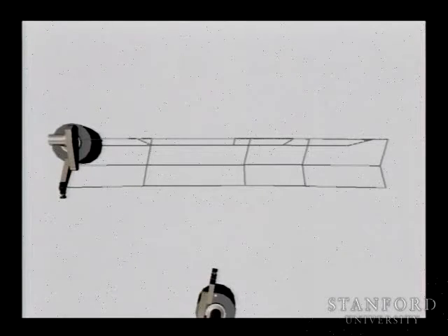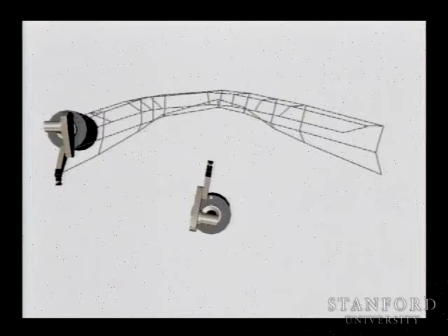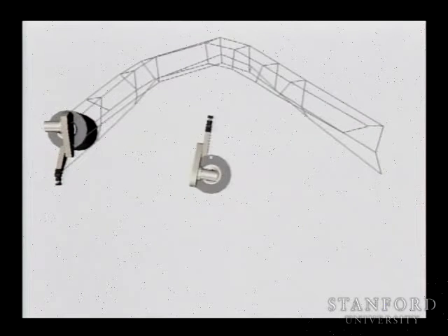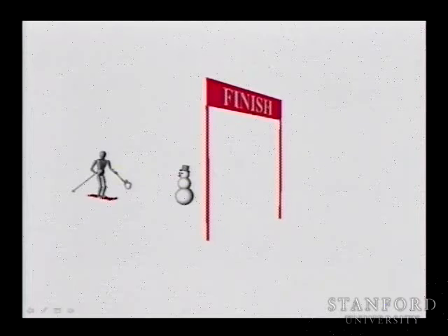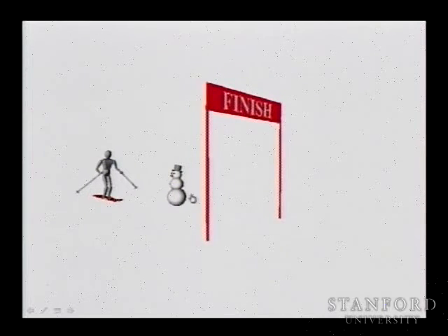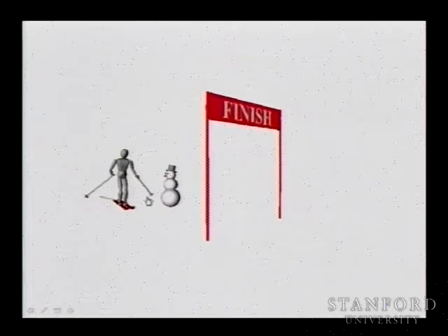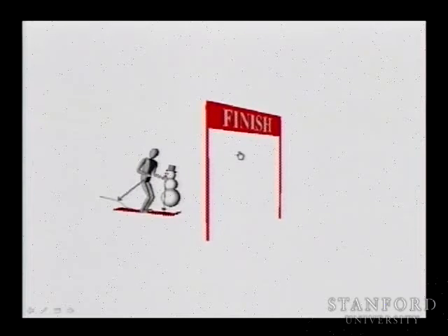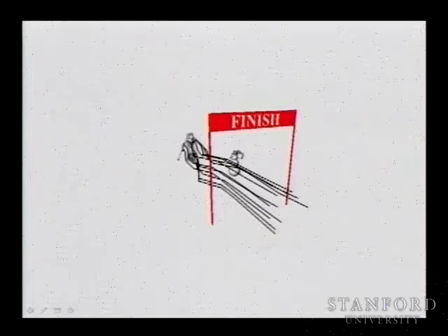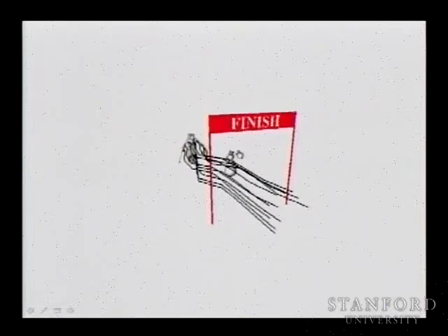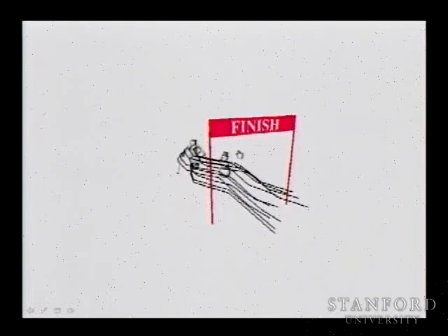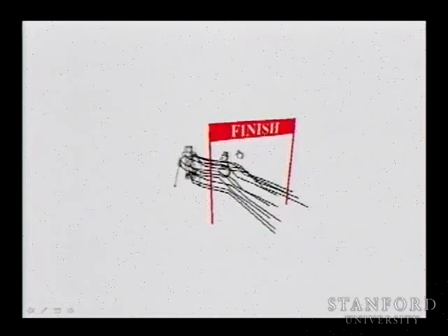But if you have a global plan, you need to deal with the full plan so that you will not reach a local minima, and we then apply this technique to modify all the intermediate configurations so that a robot like this would be moving to a goal position through this plan, and when an obstacle appears or when the world is changed, the trajectory is moving, the hand is moving, and all of this is happening in real time, which is amazing for a robot with that number of degrees of freedom.